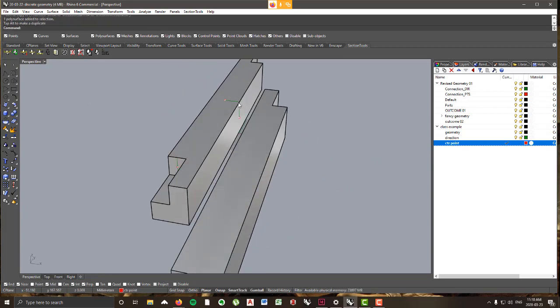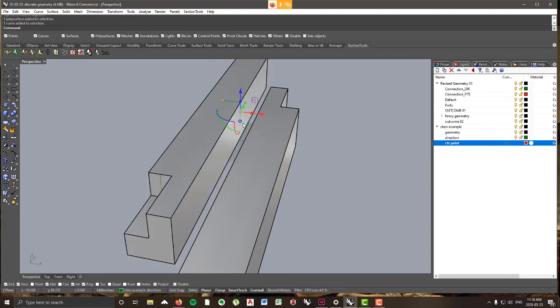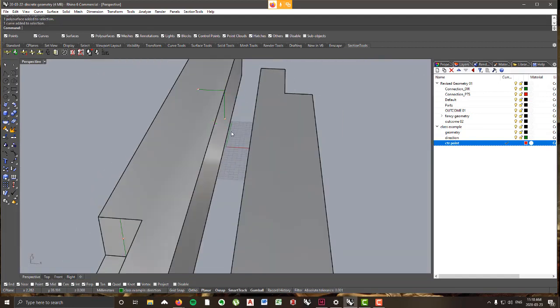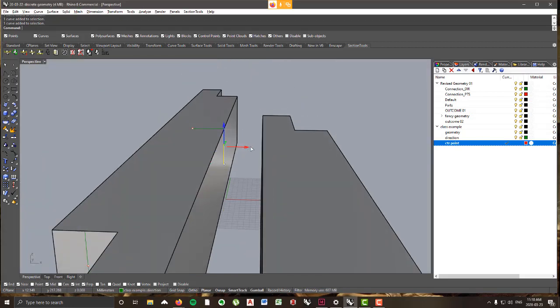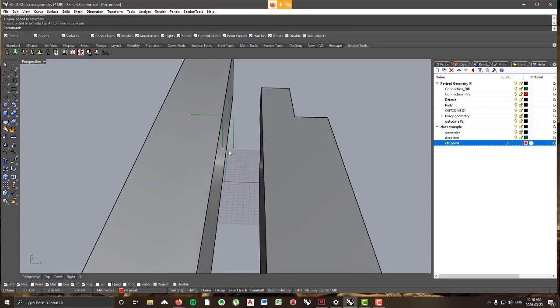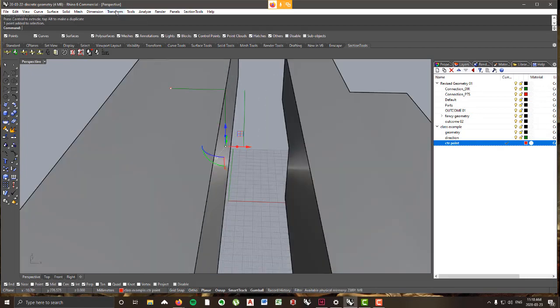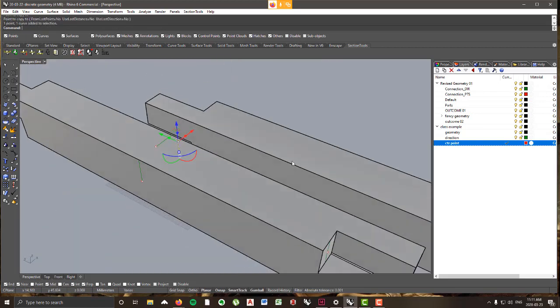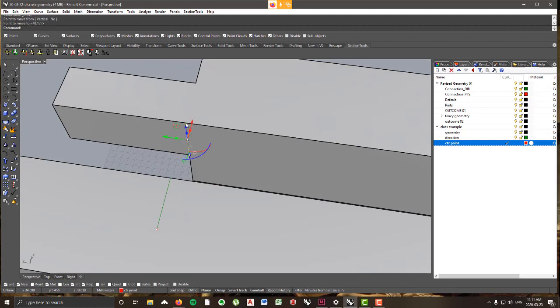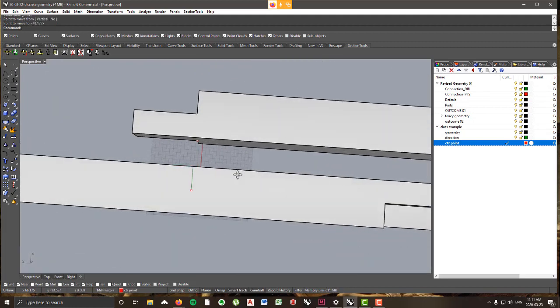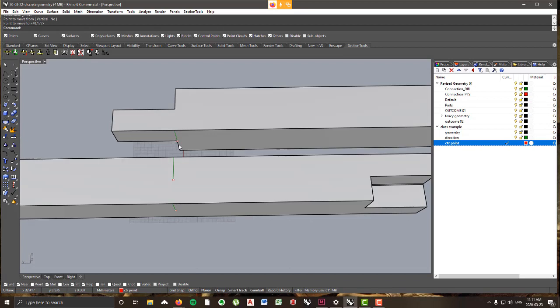And then I just like finding a pre-existing connection point on my original geometry. So I'm selecting this original point and line here. I'm holding Alt to drag it over. So let's select the point as well. Transform copy. I'm just taking this point and line and I'm going to move it over, transform move to right there. So that's making the connection.